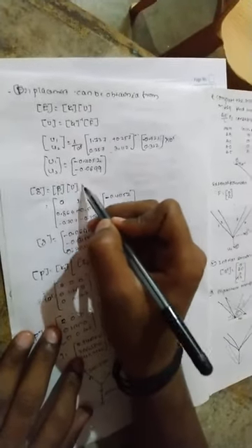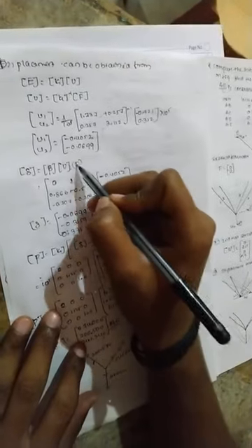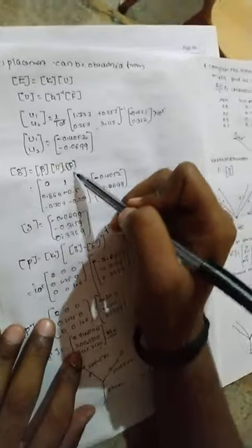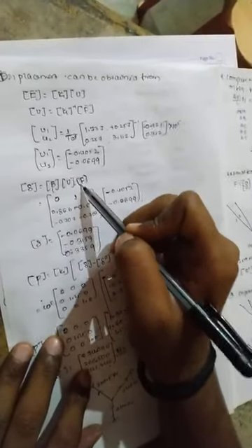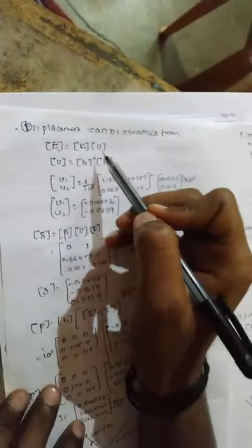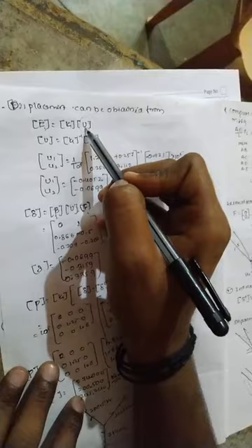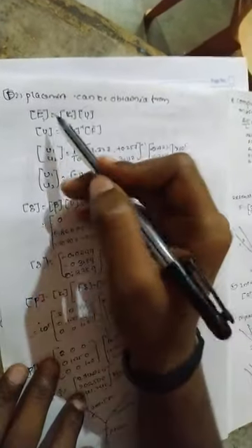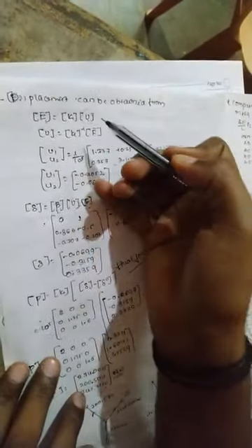Once you get the F bar, the next step is displacement. To find the displacement, the delta value should be beta into U. That U, or we consider it the F matrix, because here we are taking it as F. You know beta already; you have to find the F matrix, which should be K into U. Here we are going to find the U matrix, because U is the deformation or displacement.